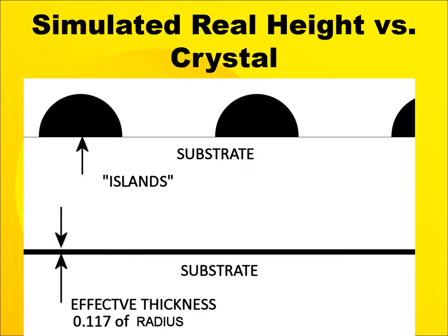Now, one thing to keep in mind is if we're controlling the thickness of our deposition with a quartz crystal monitor, it's seeing the collective mass that's deposited on it, but these are growing as islands. So what the crystal reads will be much thinner than the actual island height when they're separated by some distance because of its averaging effect.